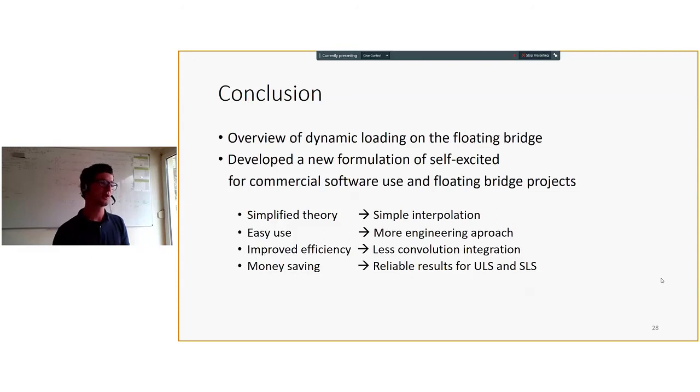And this is of course good for those time simulations which are very long. Also, this theory, in my opinion, is a big money saver for all the projects, for two reasons. The first reason is we are now able to do accurate and decent ultimate limit states calculations, which were previously not possible with quasi-steady theory, and they are embedded in an already existing framework. So it's very accurate as far as it goes for the floating bridge. As well, we have more accurate serviceability limit states, and these are also important for fatigue design and some other aspects. So the bridges with this theory will definitely be built more economically.